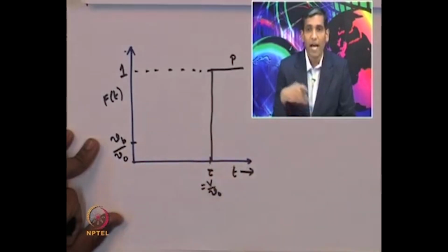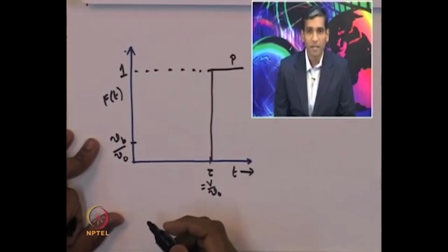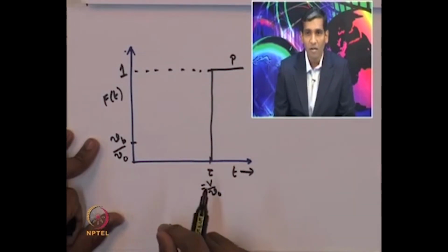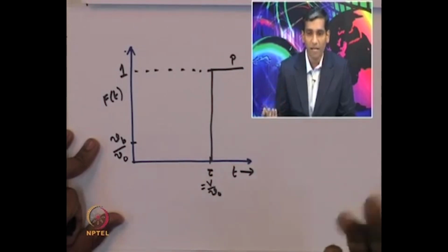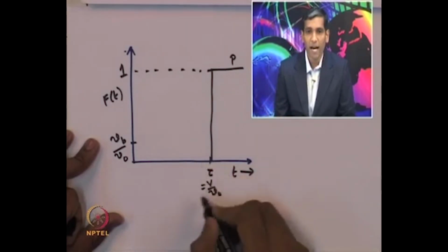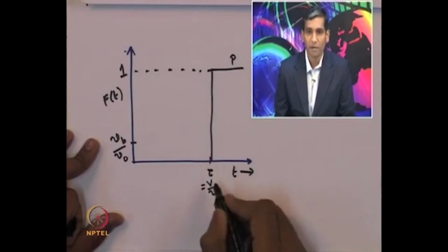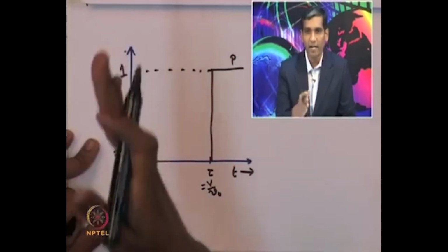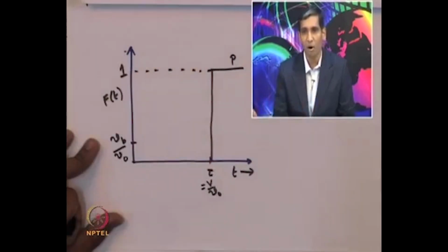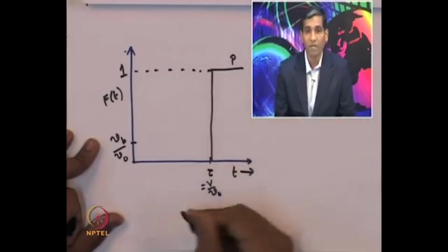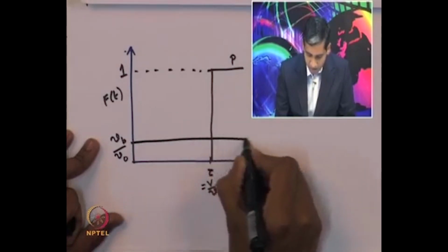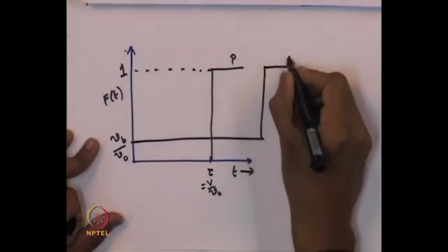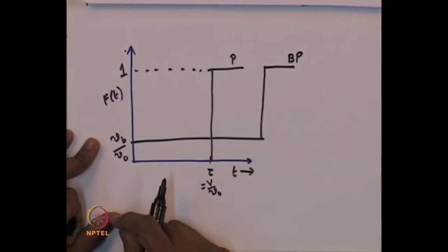So, that tells you the extent of bypass which is present in the reactor, and because the space time is now larger than the space time of the reactor under perfect operation, or if there was no bypass, the fluid stream that enters the reactor is going to take longer to leave the reactor as compared with the perfect operation. Therefore, the f curve will essentially look like this if there is a bypass inside the reactor.